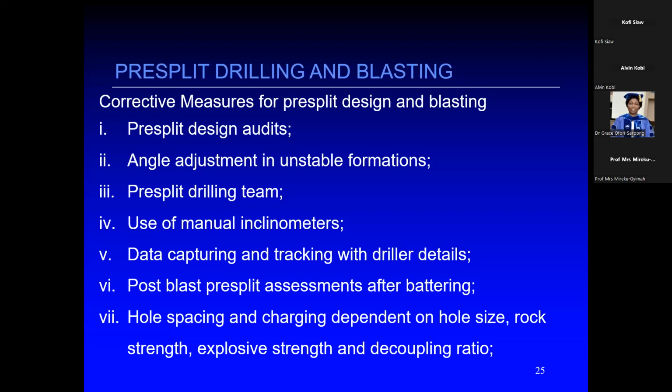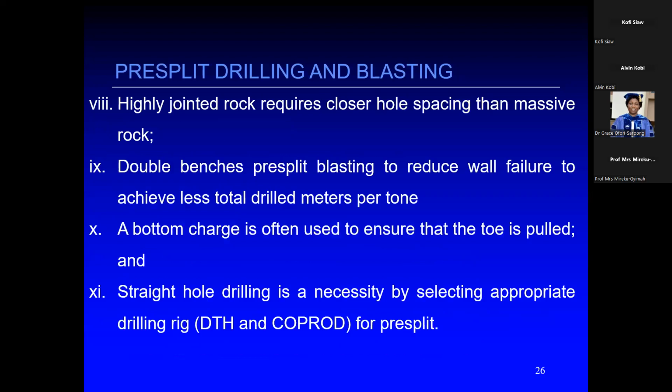So we can also optimize this hole spacing. Then we also have highly jointed rocks. If you have highly jointed rocks, you should also look at the spacing. Then we can also use some of these drill rigs, such as the DTH, in order to minimize these deviations.